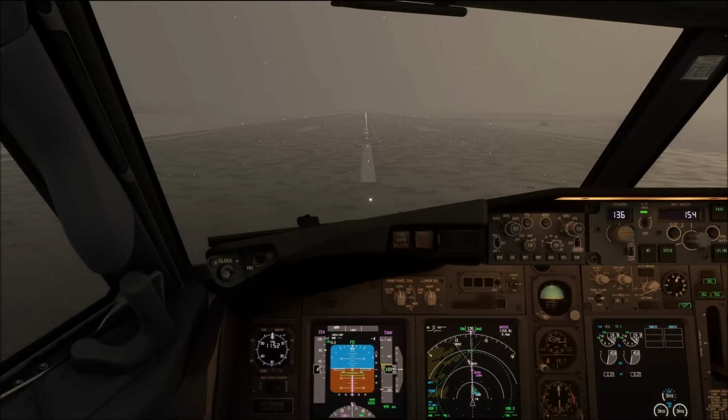And high vibration can be expected during the engine run-up due to asymmetric shedding and before all the ice has been removed. Vibration levels should return to normal before a takeoff is initiated. Note: fan blade ice buildup is cumulative. If the fan spinner and fan blades were not de-iced prior to taxi out, the time the engines were operating during taxi in should be included within the 30 or 60 minute interval.